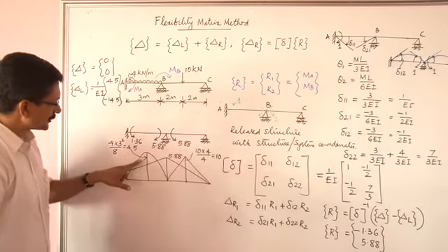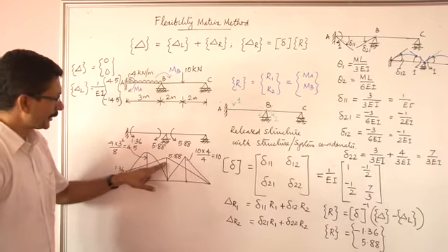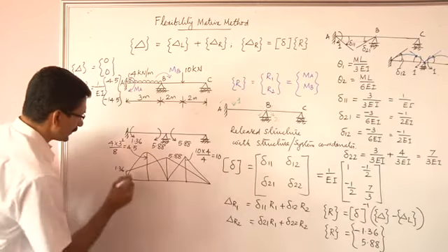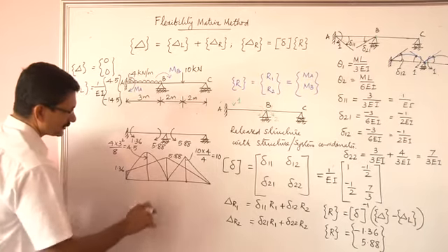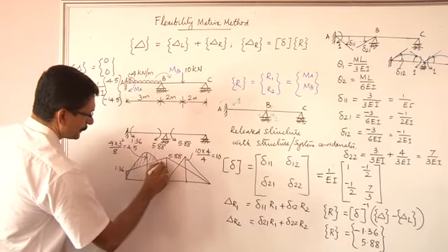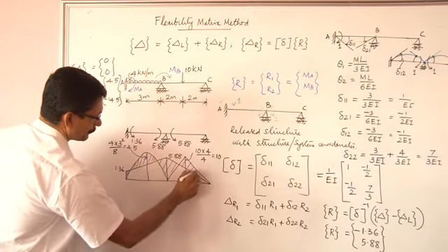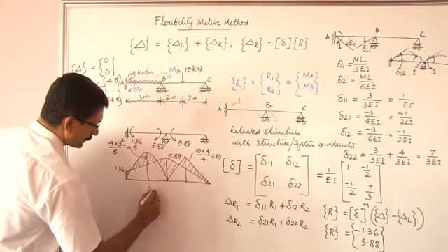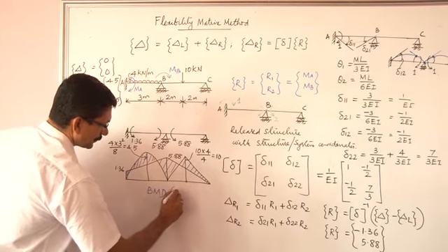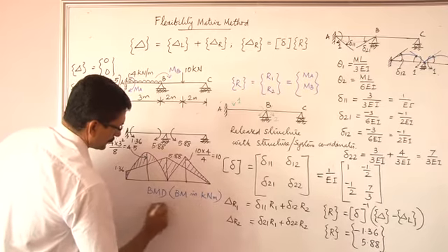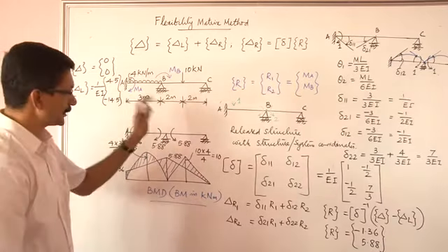Now because the simply supported bending moment diagram and the support bending moment diagram are of opposite nature, the disjoint portions are supposed to be shaded. That is, the common portion is actually cut off, and the disjoint portion is the actual bending moment diagram. So the shaded portion is going to be the actual bending moment diagram. We can find the ordinates everywhere in the beam. Bending moment is given in kilonewton meter. So that is the final step in this procedure.